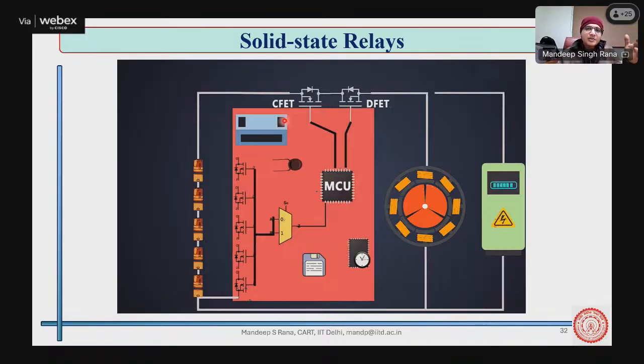In any circumstances, we usually do not turn on both of them together. That's the philosophy. But truth is, when we turn on either FET, we do have a tendency to turn on both, not relying on the diode to transfer the energy. For example, in a discharge FET turn-on situation, the energy goes through the diode of this FET, but if the FET is also turned on, the energy does not go through the diode.